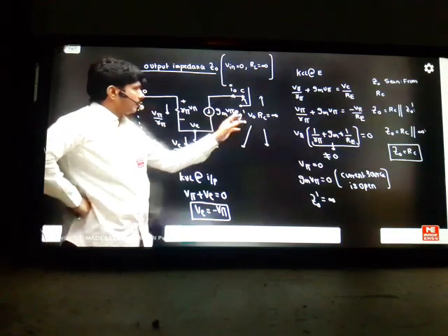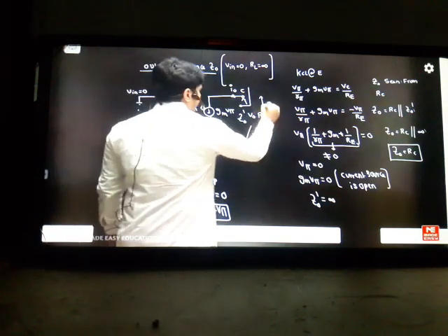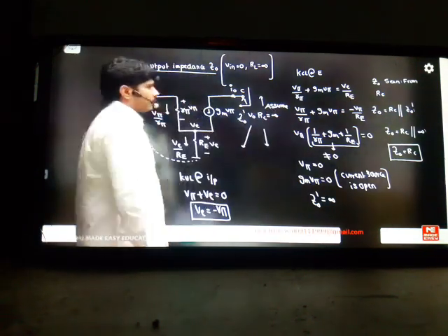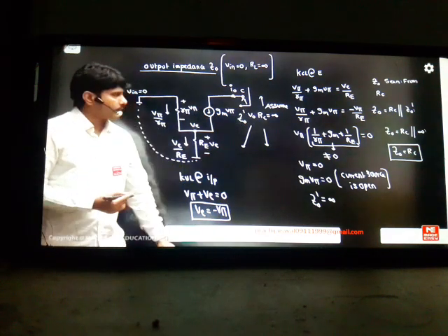RC before it is infinite. If you consider RC here, it becomes RC parallel to RL. This is the only assumption we have made here. To find this answer, we assume RC is infinite. After that you just connect RL in parallel and see the answer. It is infinite parallel to RC, so the answer will become RC. So this completes my second proof for you.